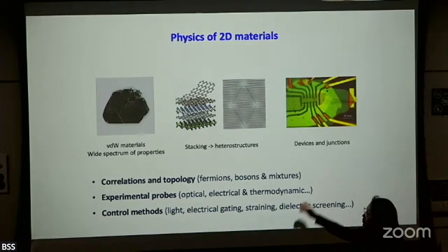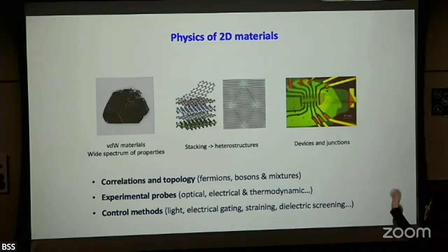So once we have this, we can do lithography. You probably have seen a little bit from Philip Kim's talk. So we shape the sample into some structure we like. If you want to do transport measurements, magnetotransport measurements, you shape it into a Hall bar. So you add those electrodes, put on gates.